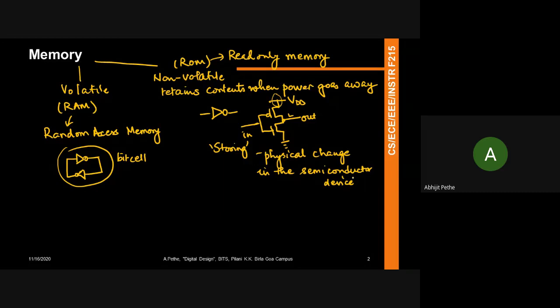So when you plug your USB stick into your computer, the power supply for that USB stick comes from the computer, and that starts your access circuitry and everything, so you can use that to read and write onto the USB. But the main memory in the USB is a flash memory, and how a flash memory stores a 0 or 1 is it actually changes the conductivity of a particular material in the device.